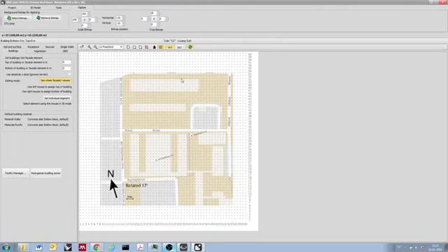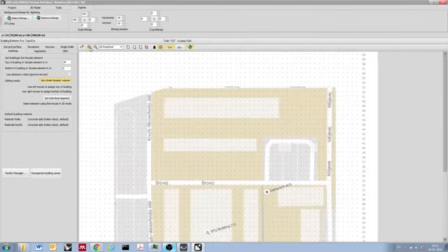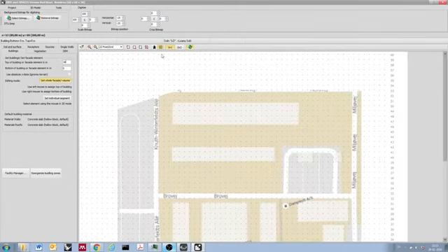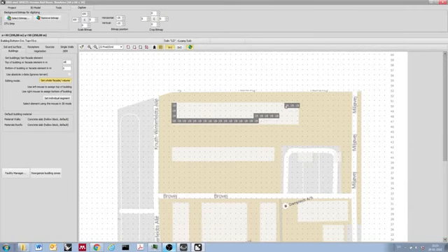Now I will begin to draw my buildings. In this tab over here, we will set the building height of our buildings. To begin with, I will start drawing this building. This building is 18 meters high. I write 18 here. And I'll just zoom in so we can see slightly better what we're doing. We can choose between 2 and 1 pixel drawings, and just by left clicking I can choose in which pixel I want to be a building 18 meters high.